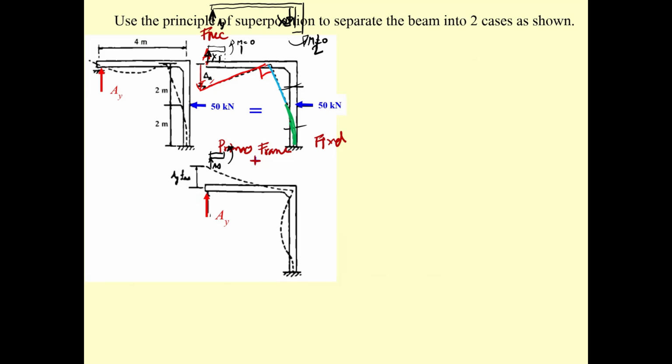If this one has a support, this one would be 0. And the same, this one would be 0. So all the members must be bent, and it should bend out. This is not correct. It should bend out. Out of what? Out of this one. It should bend like this one. And after that, this one still keeps the right angle.